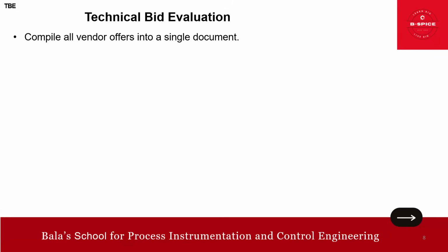Similarly, for a transmitter, you can check the range and the pressure requirement, and also the type of accessories, such as the transmitter LCD; we need an LCD display. Likewise, you need to come up with the criteria and list them out. What I want to tell you is, this is more of a generic analysis.